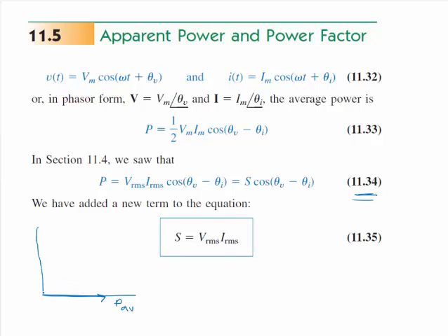And there is an angular part of that right here, which is the difference in these two angles right here, the theta phase angle of the voltage and the phase angle of the current difference. So this angle right here is right there, and so this power and this cosine of that to give you the power average is called the power factor. So there's our power factor, and it says how much of this power is real and being dissipated by the real part of the load.